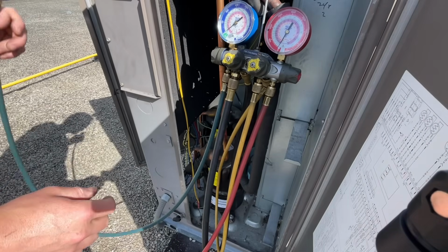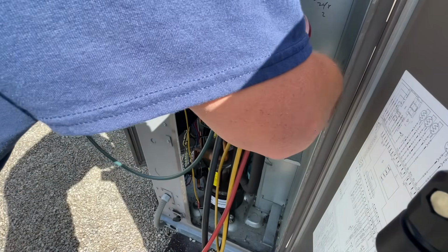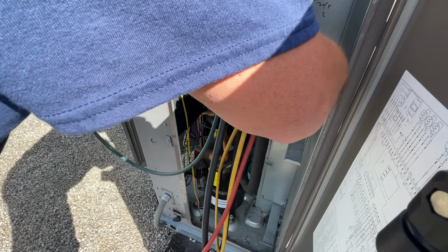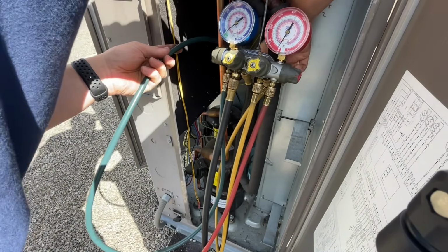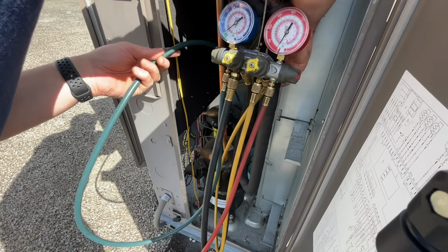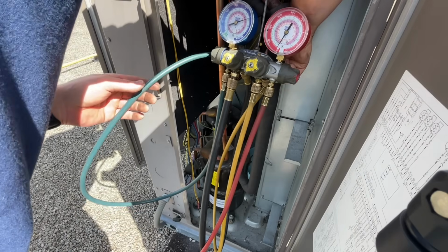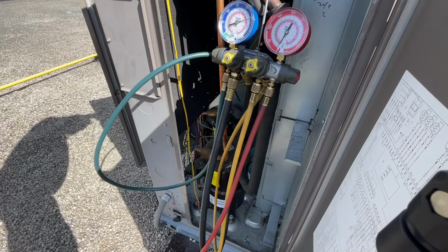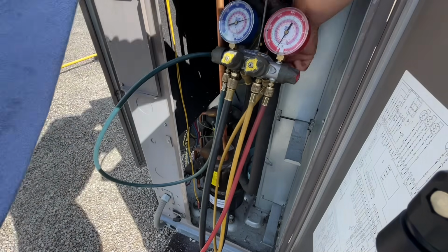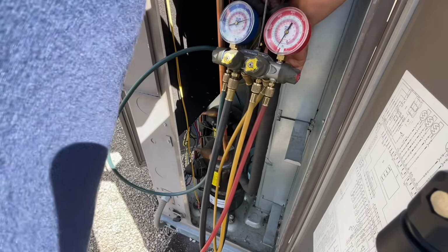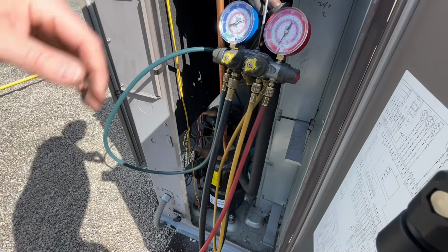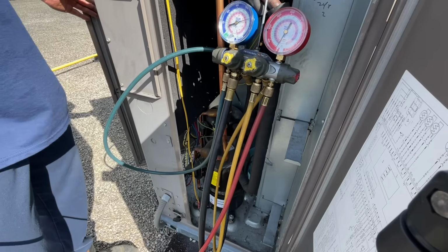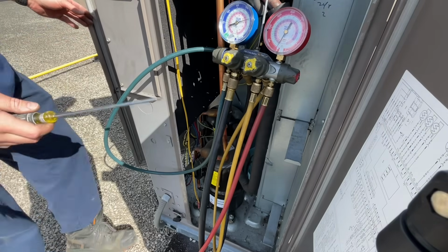All right, before we go replacing that motor, we're gonna throw our gauges on and make sure we still have pressure in first and second stage, because I'd hate to promise them everything's gonna be resolved when it won't be. So yeah, there we go. That's circuit number 1. We have pressure in there. And you know what? We might as well even bump these on. Let's turn the unit on and I'll bump the contactor quickly and make sure our compressors work.